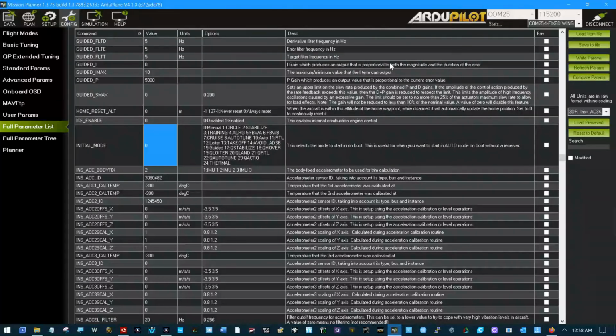I will proceed to figure out why the same hardware ESC calibration works in Arducopter and does not work in Arduplane. I'll probably find that in recent versions of Arduplane it's not required anymore. Something like that. I'll have to dig that out of the documentation. I had no idea until this video tonight that there were differences with the same platform and hardware with different firmwares. But I did have my problem exactly like I demonstrated it with the Mini Talon. And this is how I got around it.